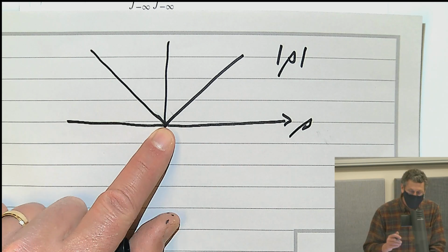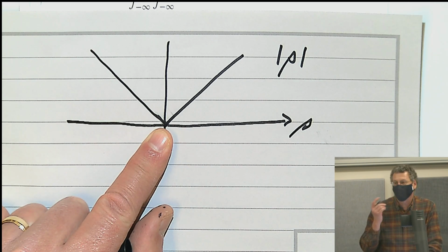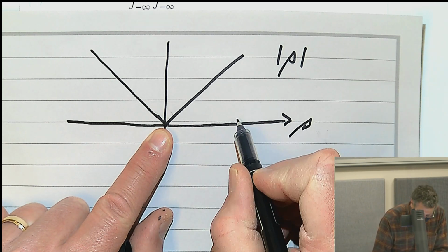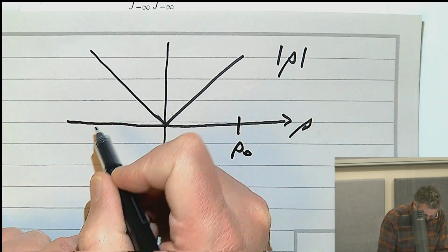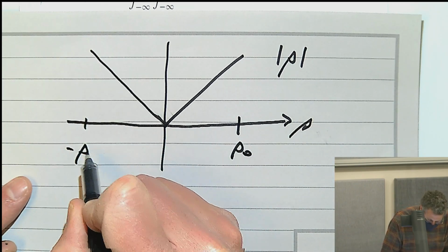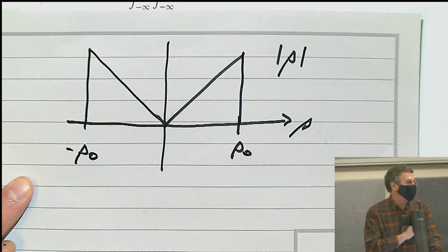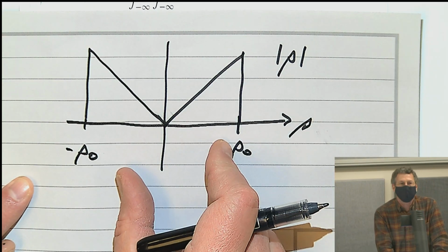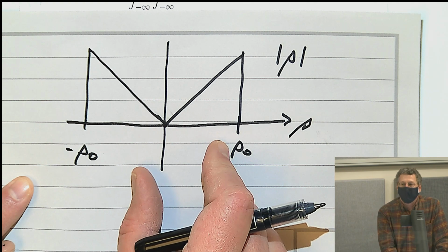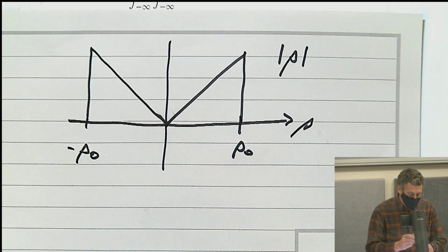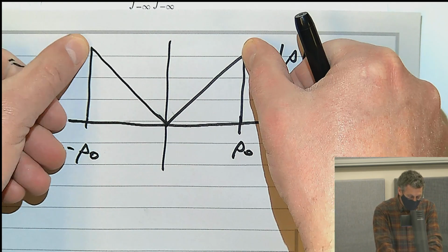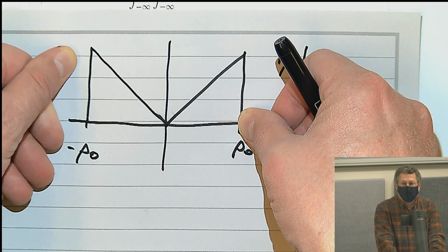So what I do is I make the assumption that the signal is band limited to some maximum frequency, we'll call it rho 0, and we cut it off. Now I can take the inverse Fourier transform of this. Working it out analytically isn't too bad, because I know the inverse Fourier transform of a rec is a sinc.